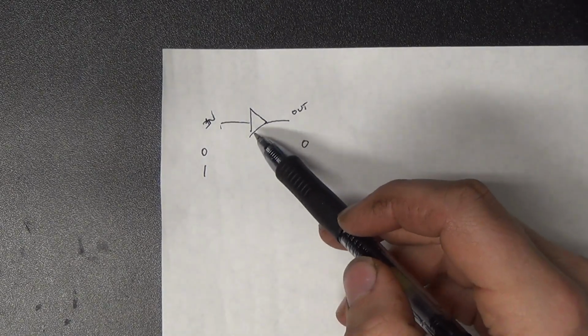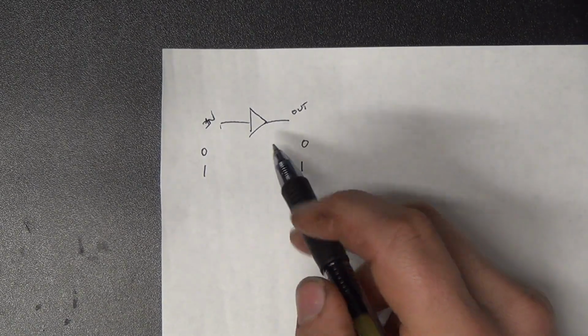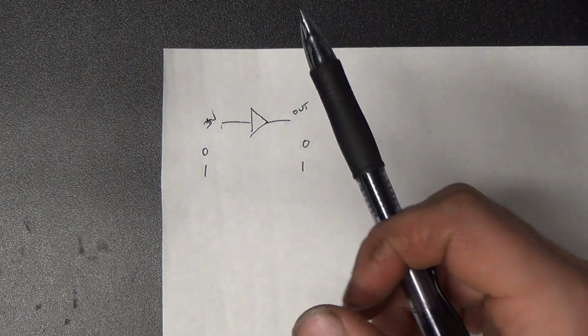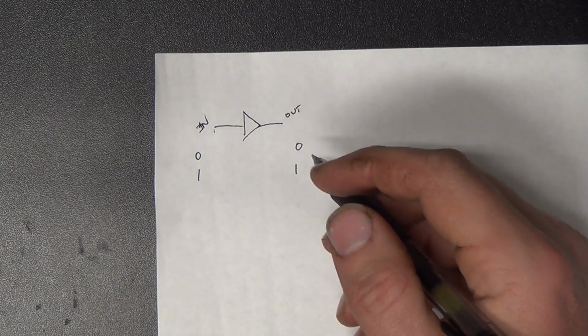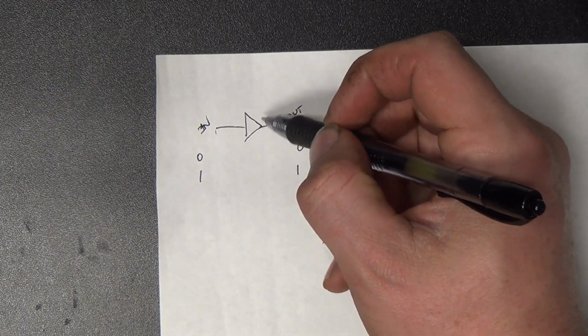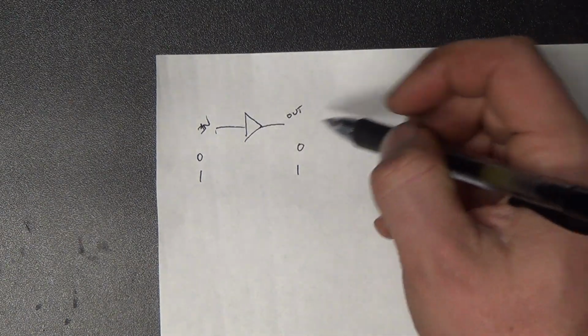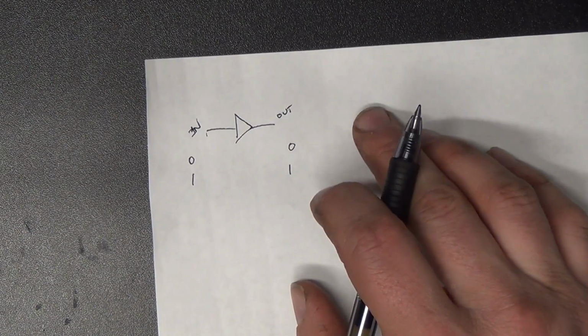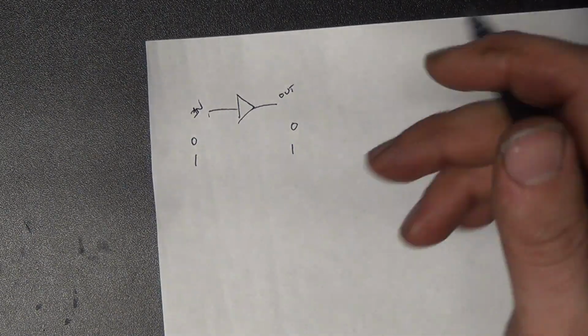So we can use buffers like this to interface these kind of anemic, current-source-wise, CMOS chips to the big bad analog world. These buffers allow the circuit to sink a whole lot more current, and drive a whole lot more devices out there on the bus. So that's all happy and good, right?